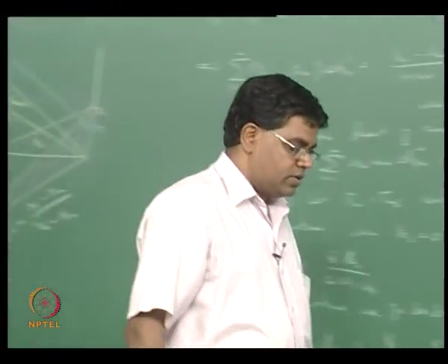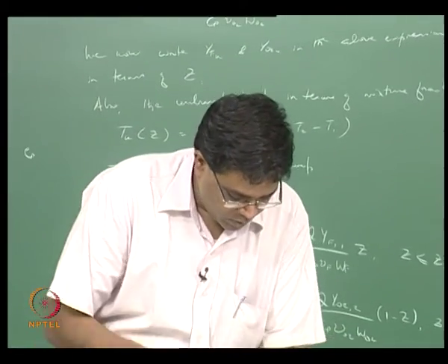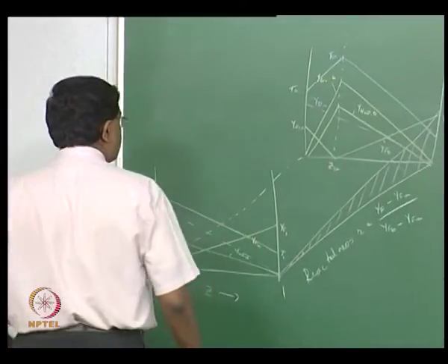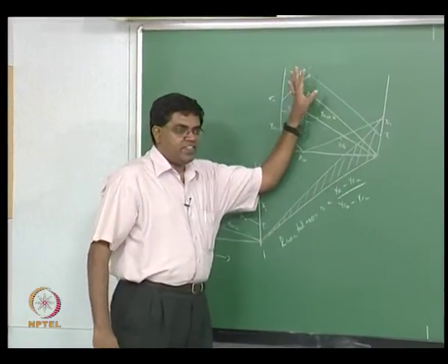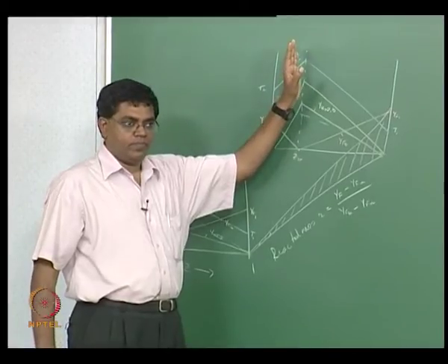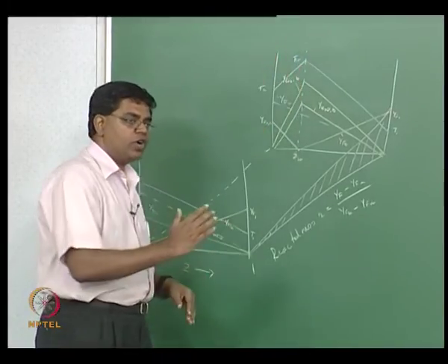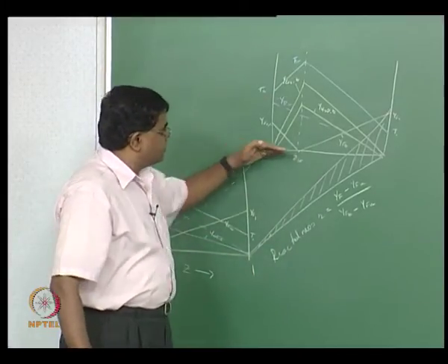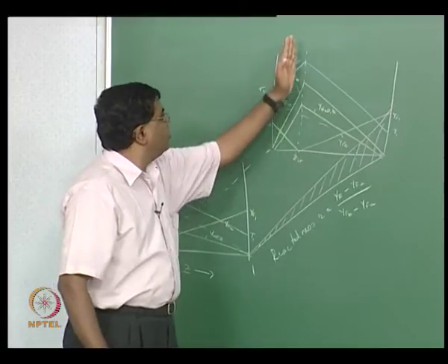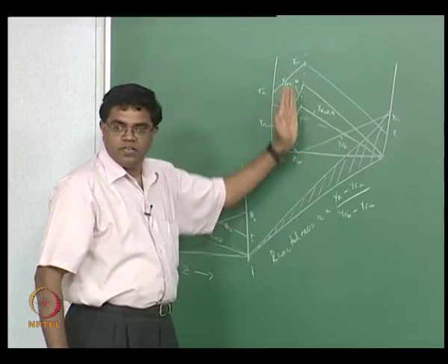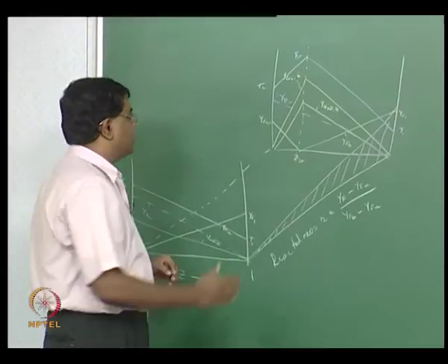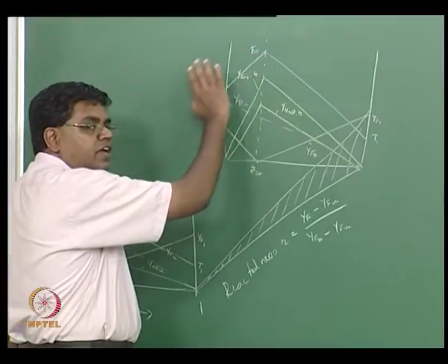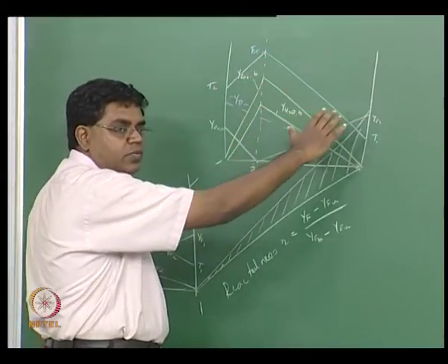So if you think about it, this is like what we were saying for the vicinity of the Burke-Schumann flame. So in the Burke-Schumann flame, if you have a diffusion flame sheet in the Z axis, it's going to be located at Z equal to Z_st, and from Z equal to Z_st the temperature is going to fall on either side, on the fuel rich side one way and the oxidizer rich side the other way.